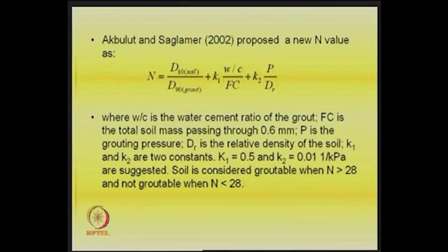But then some more people have been working on these lines, particularly when you try to do a very big project. Say for example, there is a big dam, an earth dam coming up, or a rockfill dam or whatever dam, then the foundation should be stable, there should not be seepage in the foundation, there should not be bearing capacity failures in the foundation and all that. How do you handle that? That is only possible if you have a proper understanding of the pore size, the grout size and some of this information. So, realizing the importance of some of these works, people have done a lot of work on this and they gave some sort of criteria.